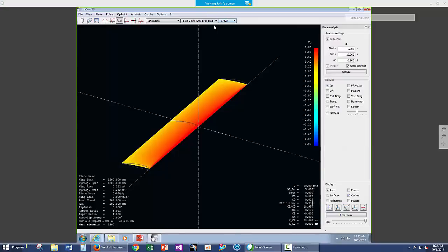In the right and left-hand corner, there's a lot of information available. Right-hand corner, velocity, alpha, we had a side slip. CL for this case at 5 degrees is 0.5. Efficiency 0.99. L/D is 18, drag is 0.28. The moment coefficients, center of pressure is at 68 millimeters. That's 68 millimeters back from the leading edge, back about here.